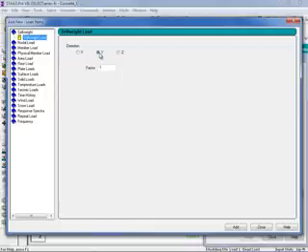For our particular model, and for most models, your vertical axis is going to be your y direction. So I'm going to select our y axis, and I'm going to enter a factor of -1, which will indicate that the self-weight should be acting in the downward y direction. Then I can go ahead and click Add, and now I've completed my assignment for my self-weight load.